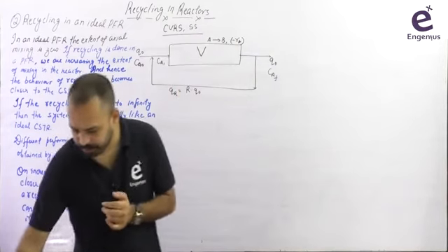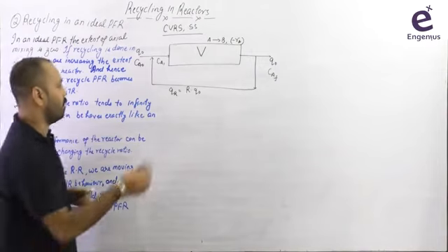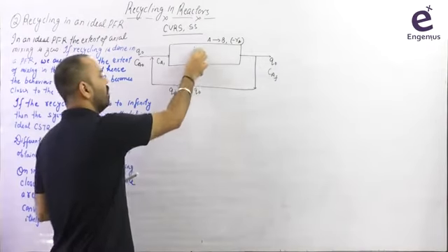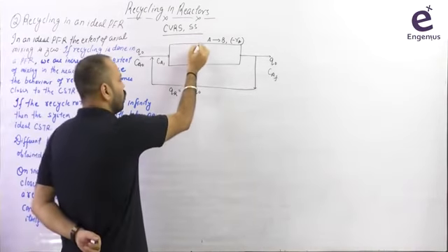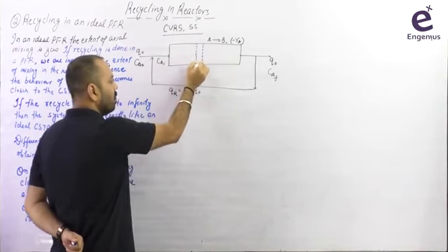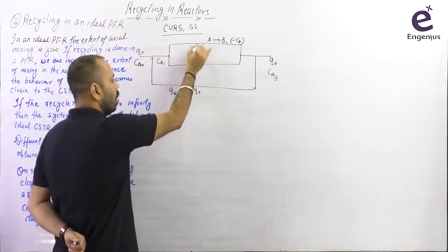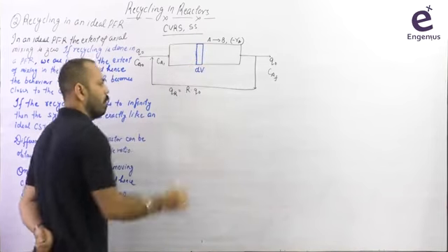Now you know that whenever you write a balance on a reactor like this PFR, you cannot select the entire PFR to write the balance. I told you why. It must be uniform. Now this recycle PFR is not uniform, so let us select an element here, a small element, and let us write the balance. The small element is having a volume equal to dV.